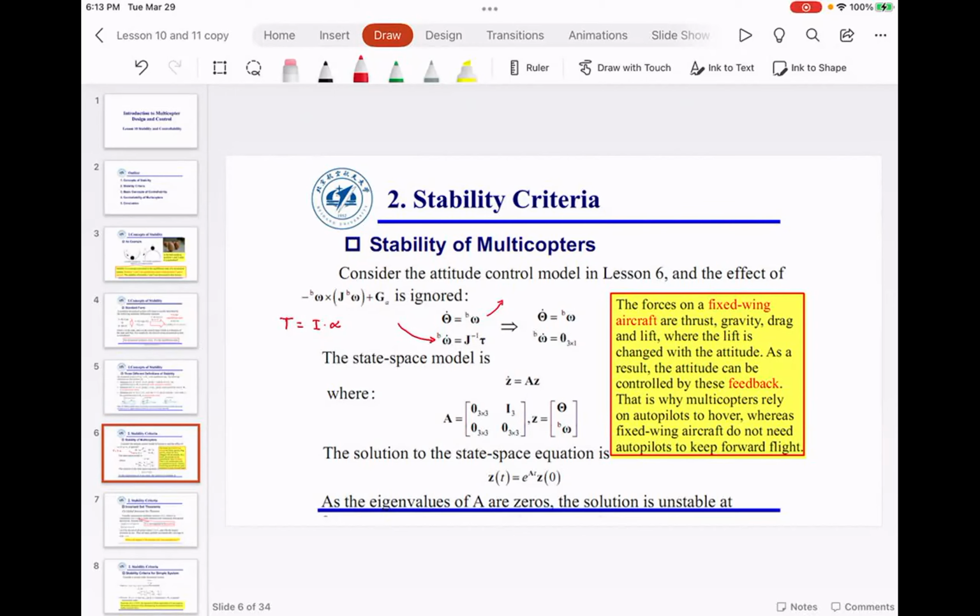What you are doing is initially you have some sort of undamped pendulum. You are making that pendulum more and more damped. So as you increase the derivative gain, you'd observe that the pendulum oscillations would be dampened. But then you will notice that you are going to have a steady state offset. For that, you would do an integral control, and then basically just making sure that integral does not wind up.